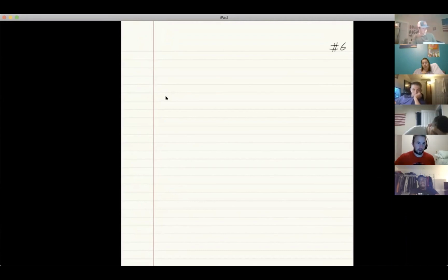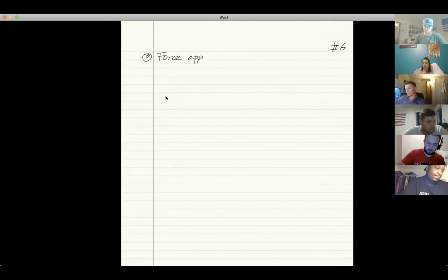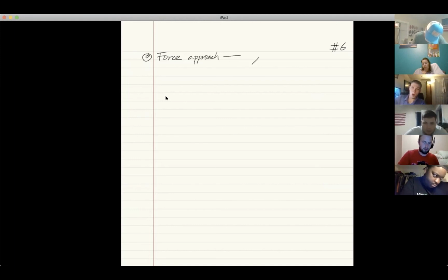And if we look at the fourth approach, I will give you the conceptual criterion. These are the criteria we use in our problem solving. So that's the big picture. You may want to take it down for your own understanding. In the fourth approach, the buckling criterion is usually this: we want to know, if the deflection approaches infinity, what will be the force? So this is the condition, when delta approaches infinity.